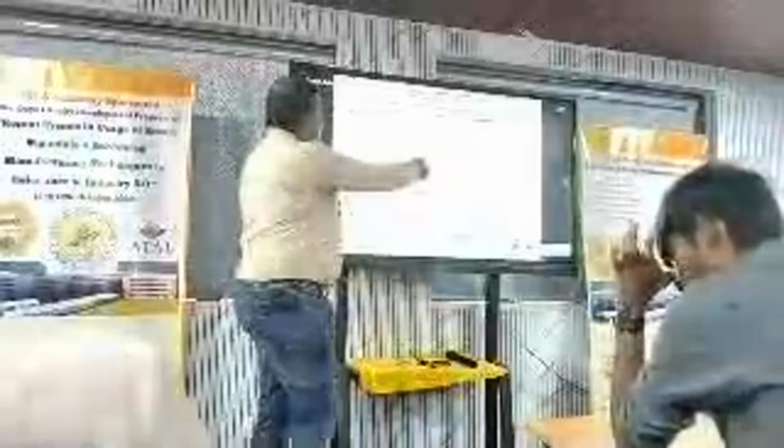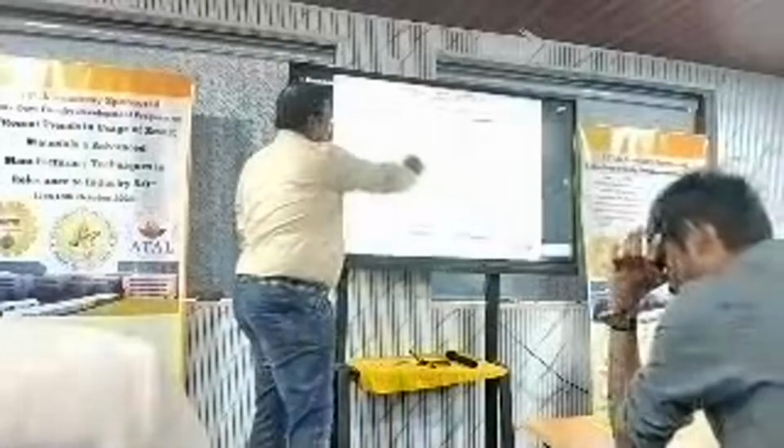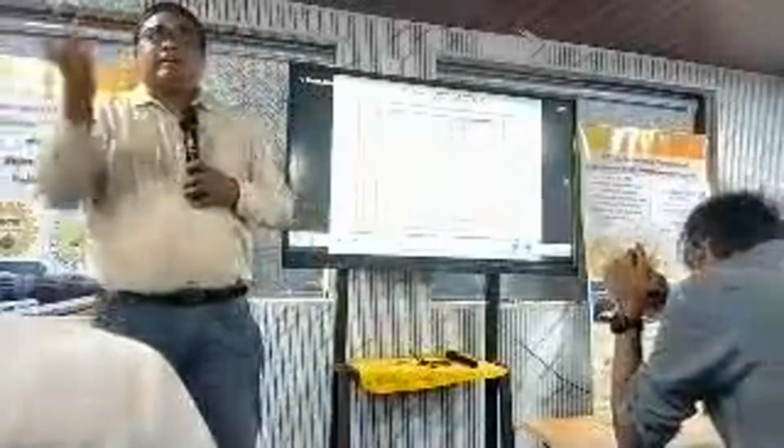If you select this graph, what will happen? This is the point, and eta 2 by eta 1 is 0.1. So we have to design the material of the bottom layer and the viscoelastic material layer such that the Young's modulus ratio is equivalent to 0.1.